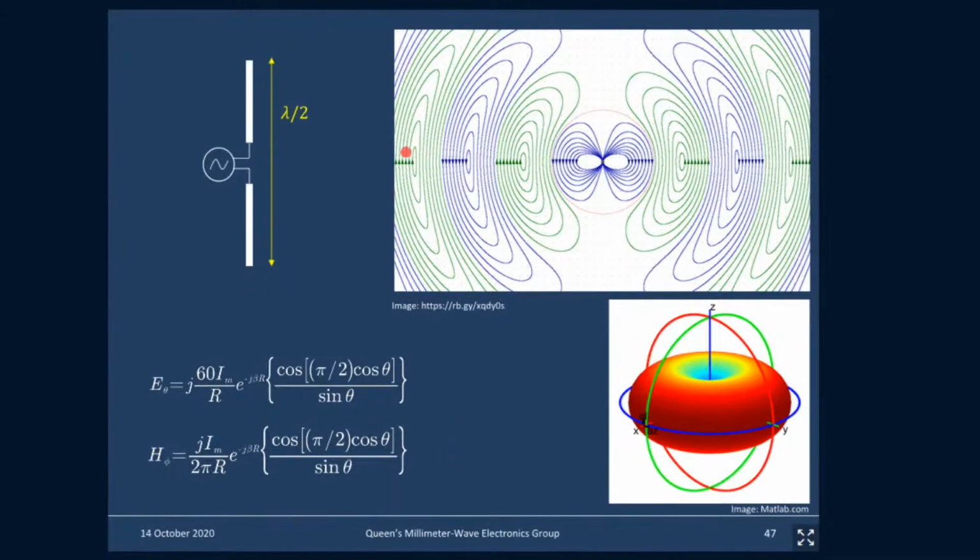But what I want to say here is that, okay, so if you want to tune the frequency of this dipole antenna, you have some choices, right? Well, the main choice is you just have to make this dimension of the dipole physically larger, right? You have to extend this somehow. This is how it generally works.